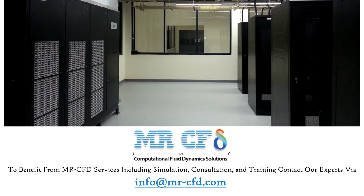The present problem simulates the process of air conditioning in an office with several computers and simulators using ANSYS Fluent software. The air conditioning system in the current model is of floor heating and ceiling cooling. In this way, the effect of buoyancy causes free heat transfer inside the office space. Due to the lightness, the hot air moves from the floor to the ceiling, and the cold air does the opposite, thus creating a circulating flow that causes the air conditioning process.